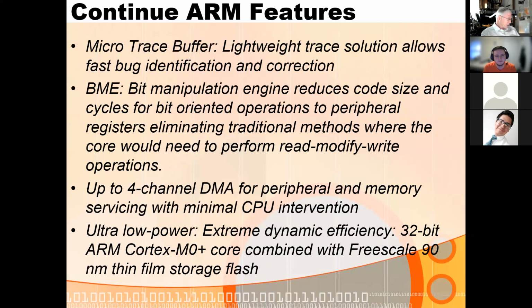Now that is changing a little bit as we get into the smaller and smaller feature sizes. As you get smaller and smaller feature sizes, the percentage of your overall current use that the leakage current makes up goes up. And so with 10 nanometer technology, although this isn't a 10 nanometer chip, it may not even be a 28 nanometer chip. I'm not sure, probably a little bit bigger than that, maybe even.